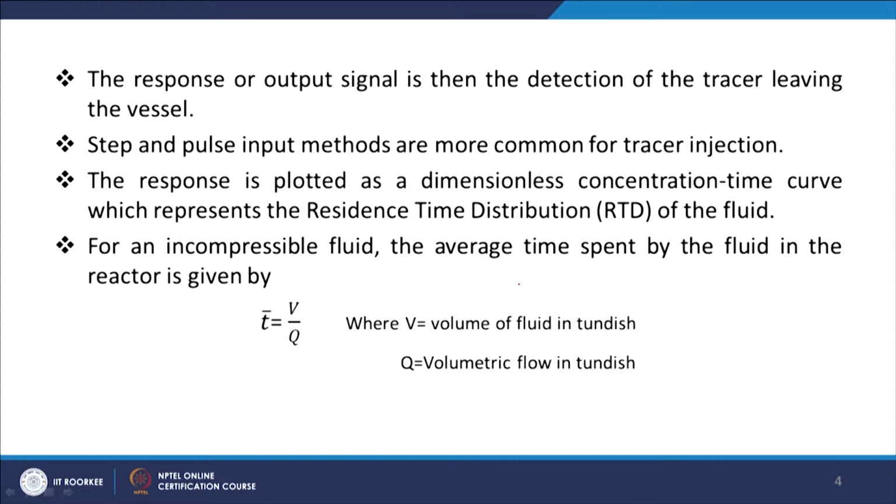When you put in the tracer, it goes through and you monitor its stay inside the vessel, then plot a graph. On the x axis you have the time, and on the y axis the concentration of that tracer, made dimensionless in certain ways, which we will discuss. This curve represents the time spent by the fluid particle inside the vessel.